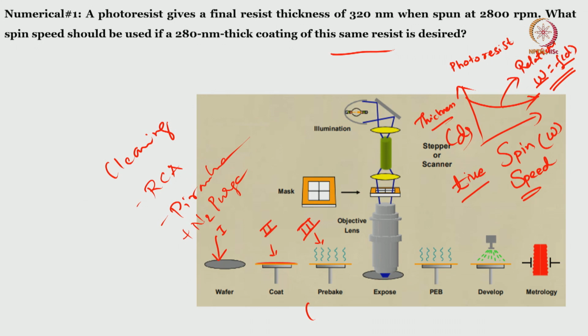For pre-bake, the temperature of baking and the time for baking, okay, both are decided. Same goes for PEB, temperature and time. Now, this PEB is post exposure bake.